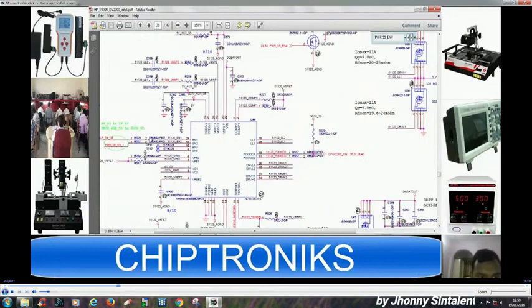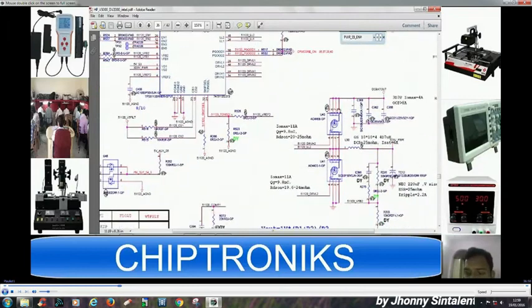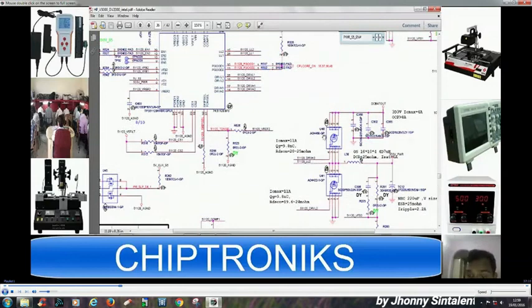the EN2 will become active. Then this 3 volt 5 volt regulator IC, having the internal drive, will generate this drive high 2 and drive low 2, and will switch these MOSFETs to generate this voltage. So if this voltage is not coming, we have to check for these two MOSFETs, the top gate MOSFET, bottom gate MOSFET, this inductor, this capacitor, and we have to check this input at the gate.